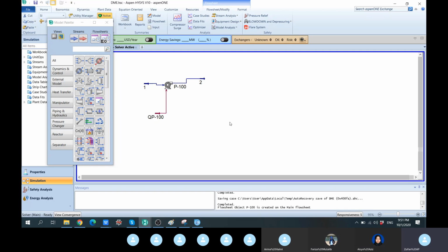So the vendor can give you that information, and based on it, it says, for example, you are not allowed to have a fluid going through the compressor at a certain level, say 200 degrees, just for simplicity. So you can increase your compression ratio while checking the outlet temperature, in such a way that the outlet temperature of the compressor doesn't exceed 200 degrees C. Okay, let's put this into practice.